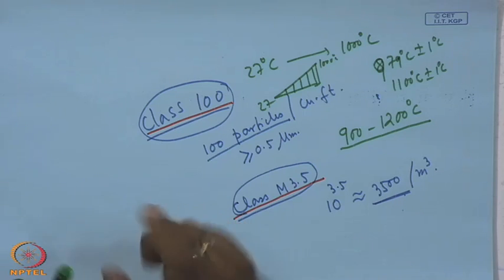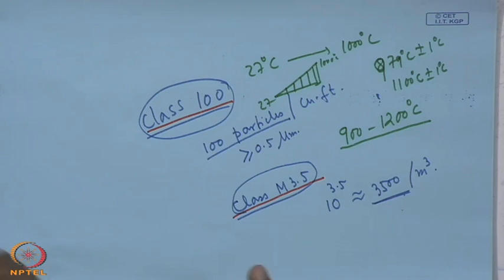the microprocessor. So, essentially we find that the oxidation furnace which is used in the oxidation process must have some computer control or microprocessor control, using which you can load and unload the wafers, you can ramp the temperature up to the oxidation temperature which is quite high, keep the temperature at that point very precisely up to plus minus 1 degree centigrade, and control the gas flow, the timing and the flow rate etcetera.